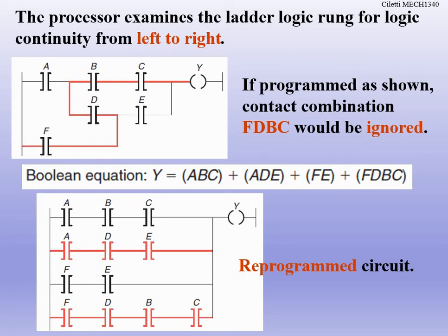You have to make sure that you're consistent with the way ladder logic works. Left to right, top to bottom. It will not retrace and go backwards through a program. It has to go in a specific order. All right, there is no way to return back as you're halfway through the program.